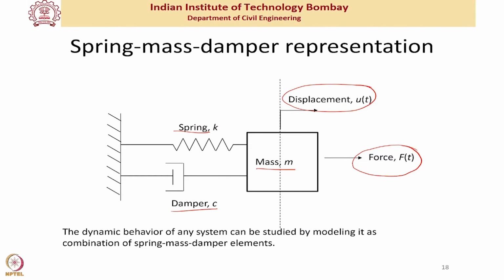Although I have shown you here a single spring mass damper system, even if I have an interconnected body, I can lump the masses and connect them with a spring and a damper like this. Each of them can be connected to each other node, depending upon the connectivity, and through this any system can be represented by a spring mass damper.